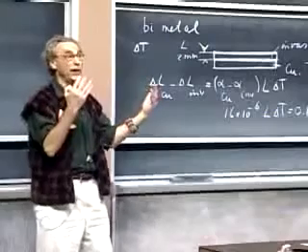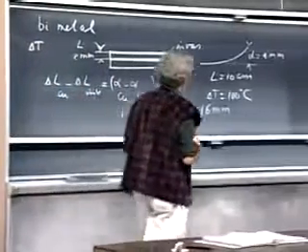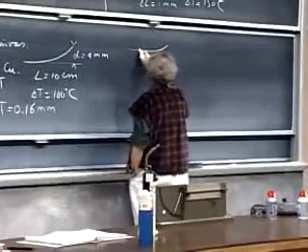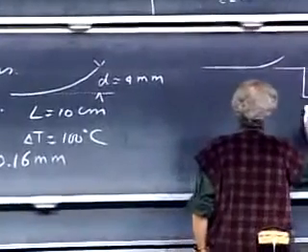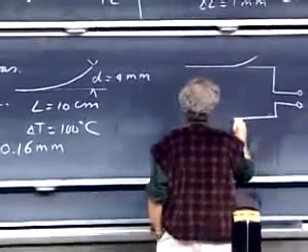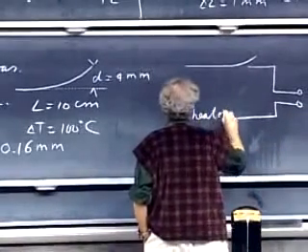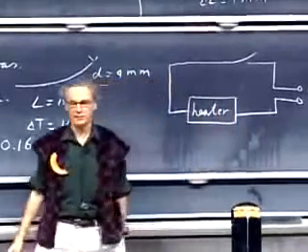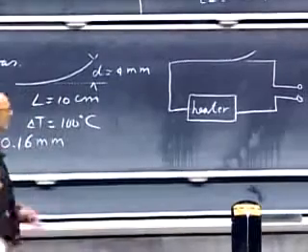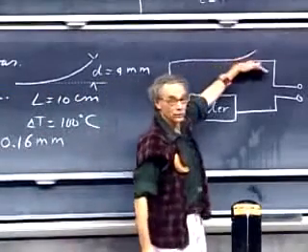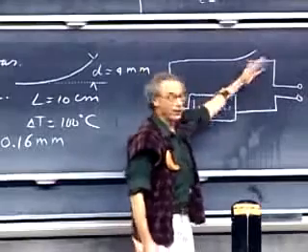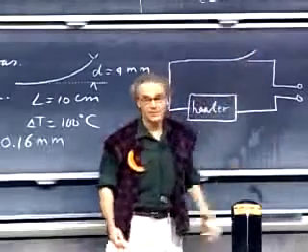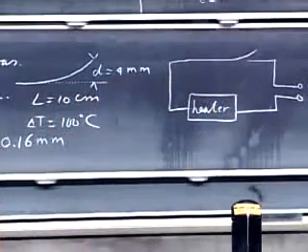So this thing is being used for thermostats. You break and make a contact in a heating system, which could, for instance, be as follows. Here would be your bimetal, very schematically. You plug it in the wall here, your 110 volts. Here is your heater. And you let it sit like that. And when it's cold, this is down. It's not curled. And the heater works. And when the room temperature goes up, this starts to curl. It breaks. And that's a thermostat. That is the basic idea behind the thermostat.